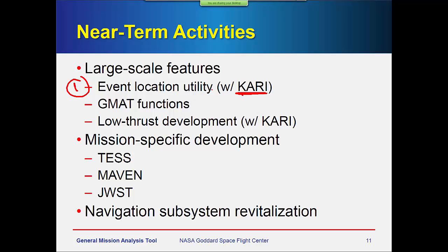Another way is, I mentioned a MATLAB interface. You can send things directly to MATLAB inside your mission and do whatever you want in MATLAB. One interesting thing we've done is, for Maven, we had a need to show a certain type of plot that GMAT couldn't do internally. So we coded a GMAT function that uses plot commands, and we just run it as GMAT's going along. So it's plotting in a MATLAB window live while GMAT's simulating. It's pretty powerful.